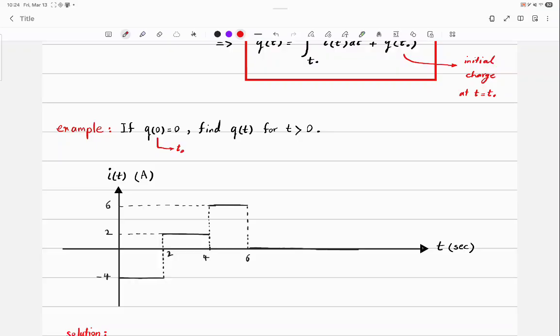What was your question? In this example, you were saying that point B you could say has a voltage of 0, and point A has a voltage of 10. How would just a single point have a voltage if the unit is a difference between two things? Unless you introduced some reference, it doesn't. Yeah, so perfect question. I said B is 0, A is 10, right?